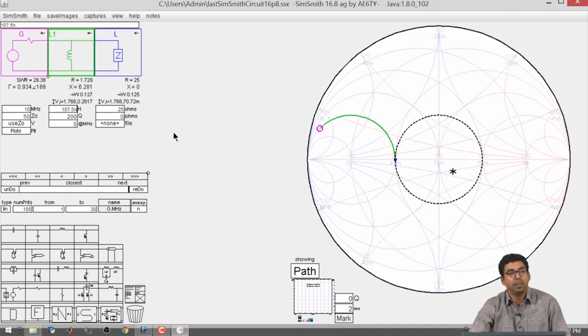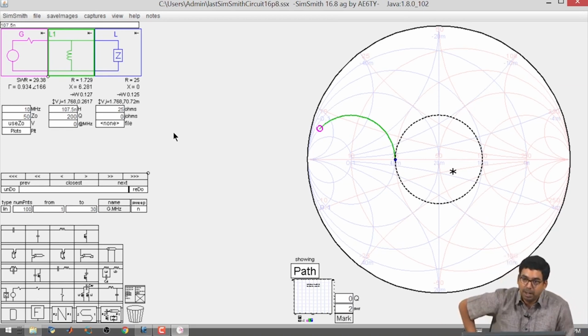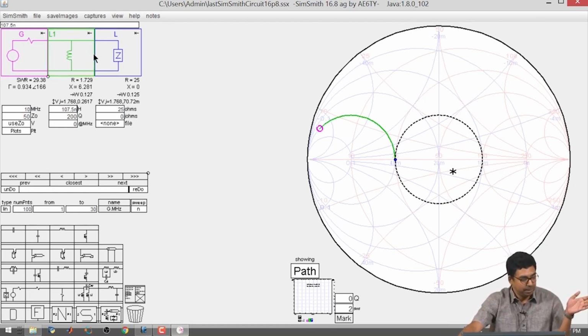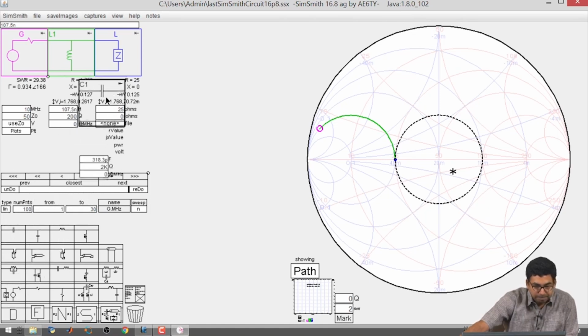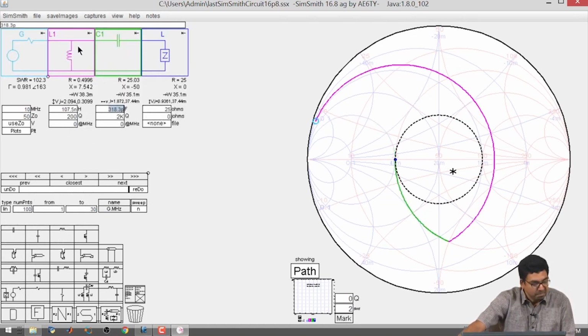Okay. So, these are the combinations possible, and one can go ahead and try to do the impedance matching without using a resistor. Okay, and we can see the consequence. Now, what we will do is we are having a parallel inductor already moving in this direction, alright, and we can always connect a series capacitance. Okay. We could do that.